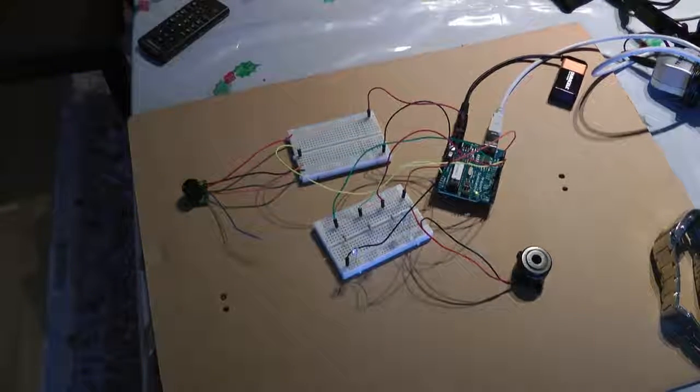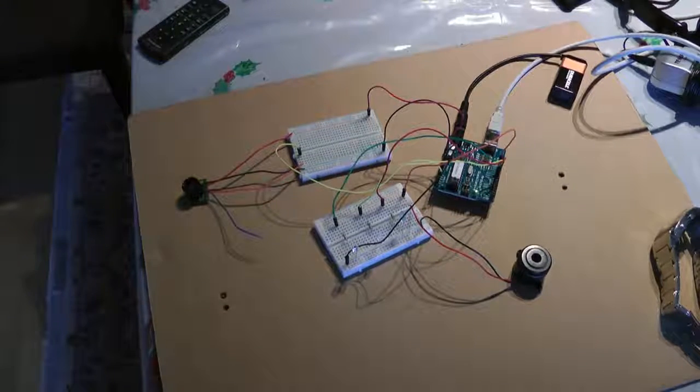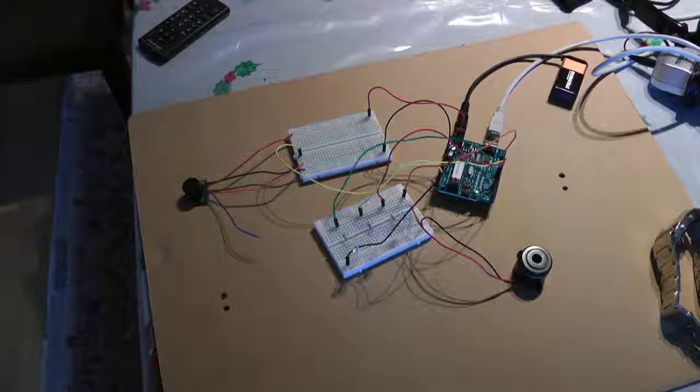Let's plug in orange to our buzzer. Okay. Do not plug the Arduino into your cigarette lighter. Even though it's 12 volts, it's not 12 volts of regulated power. You will blow up your Arduino. And by blow up, I don't mean it's going to explode. By blow up, I mean it will never work again. And even if you change the chip, it won't work. Now, how do I know this? I know this from personal experience.